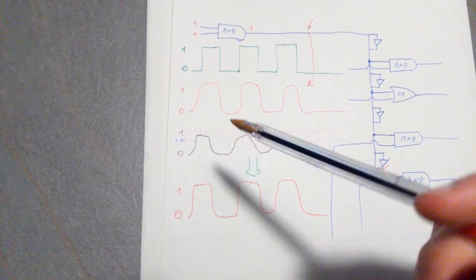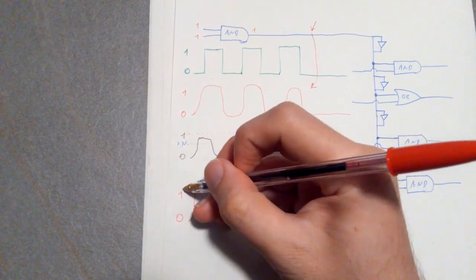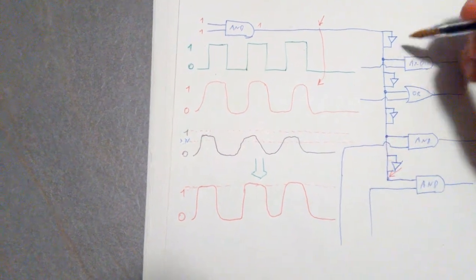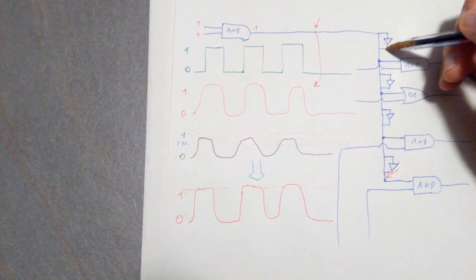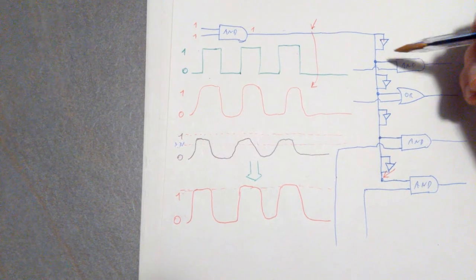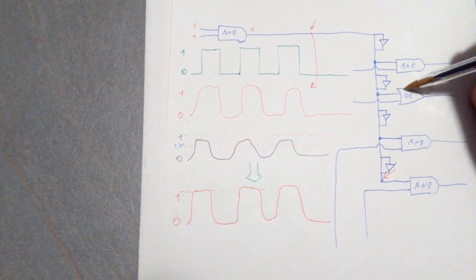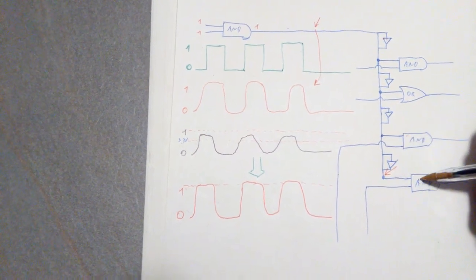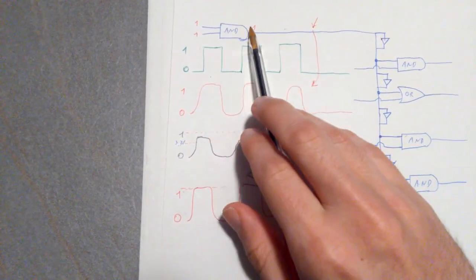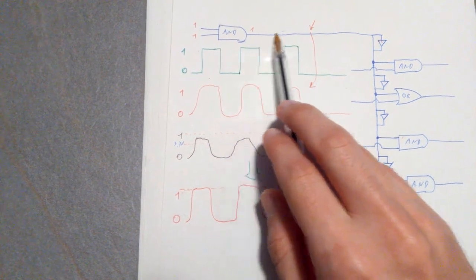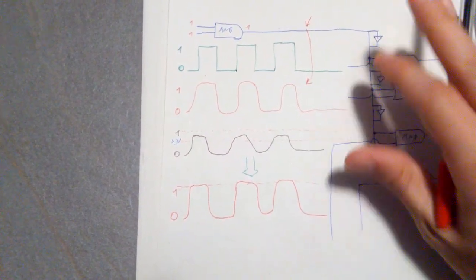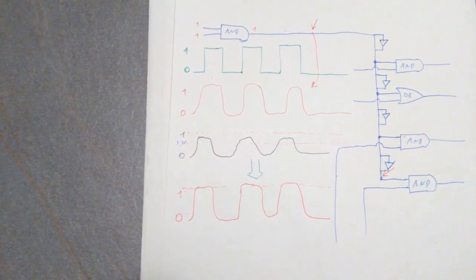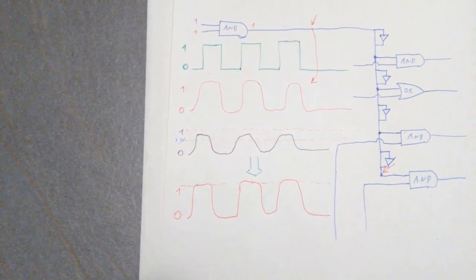And it's definitely way better, because when we analyze 1 and we expect the 1 to be here, well, it's actually here. So this way it has to travel just a little bit to get to this AND gate here, and then another little bit to get to this OR here, and another little bit to get to this AND here, and another little bit to get to this AND here. It doesn't have to travel all the way here without any buffer, because otherwise the signal was going to be degraded, with potentially unexpected things.